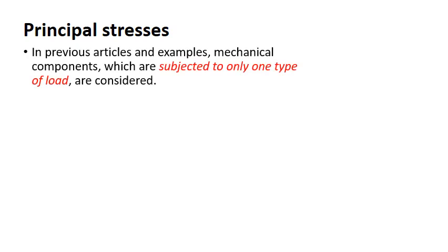See, in the earlier classes, you would have handled problems involving simple loading situations where you have only one type of loading, like tensile loading or compressive loading. This is uniaxial. The other cases of loading are bending, or only twisting, torsion loading. So it was easier for us to analyze the stress and ensure that the stresses induced in the component do not exceed the limiting values, be it yield strength or ultimate tensile strength.